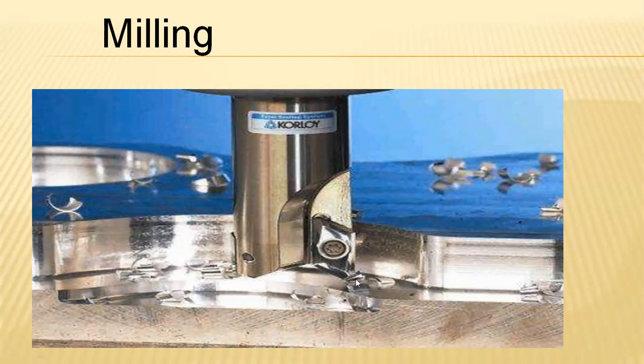Normally, we'll be utilizing steel tools or CBN tools, cubic boron nitride tools, also PCBN tools, for machining objects that have a greater HRC, which have high hardness.